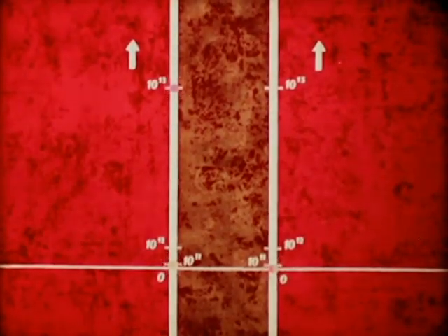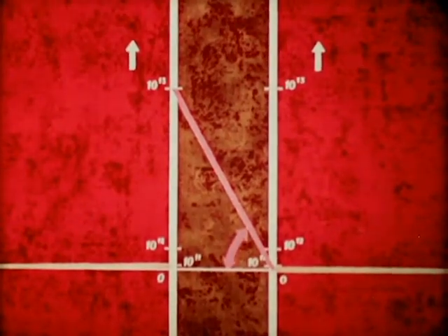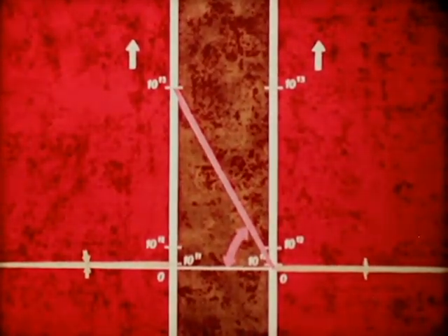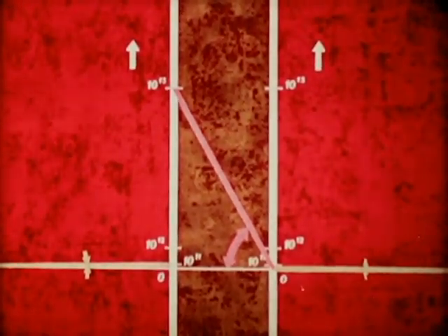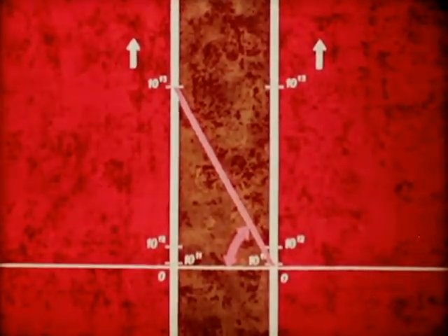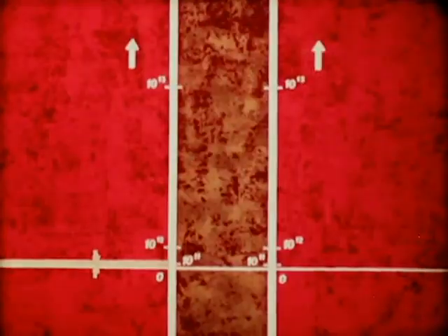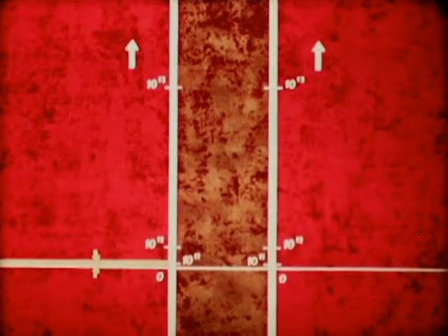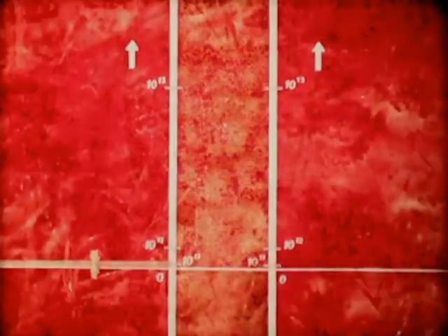The concentration curve of the holes in the base forms an angle with a horizontal axis which is large compared with the other angles determined by the electron concentration in emitter and collector. This large angle indicates that a large number of holes flow from the emitter into the base, giving rise to a large emitter current. However, as this small angle shows, there is also a small electron flow in the opposite direction, which adds to the emitter current.